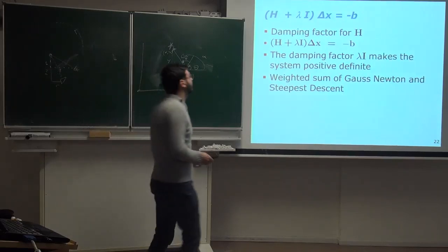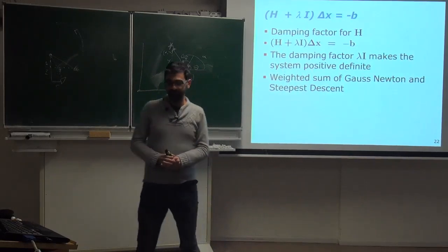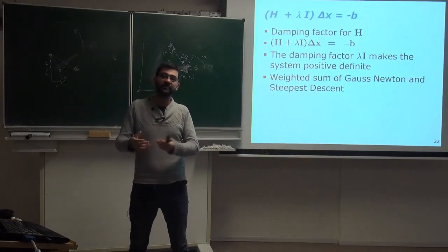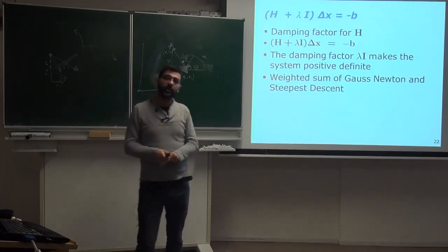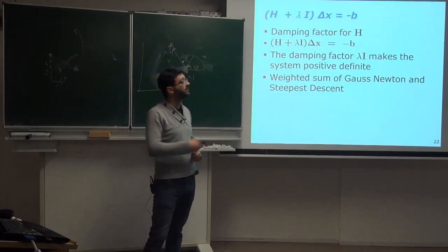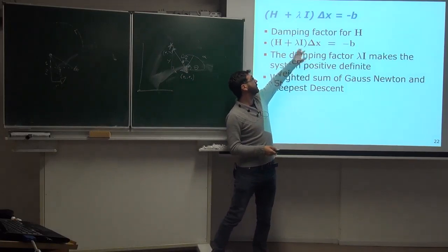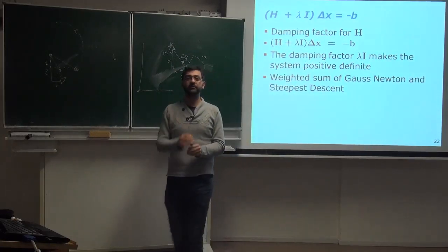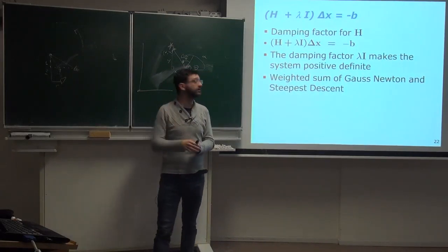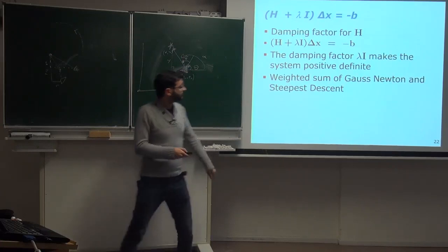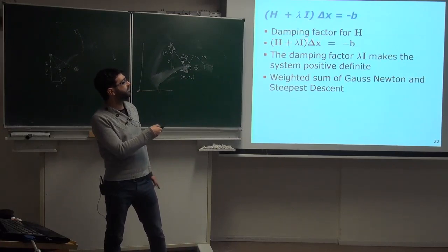This algorithm, or this way of solving the problem, is actually not new or novel only for SLAM. It's one of the standard ways of solving a nonlinear problem, and it's called the Levenberg-Marquardt algorithm. So it's at the core of Levenberg-Marquardt, and there is also a way of knowing how to compute the lambda there, so how to increase the step size, or the damping factor, and there are several other heuristics in there. But in general, you can see it as a weighted sum between